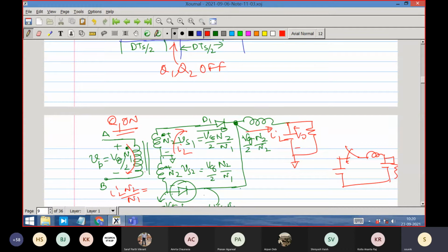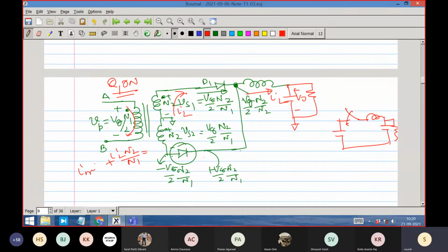That will be the first part, plus the magnetizing current, so that IMP plus the reflected load current will be equal to IP. How to determine IMP we have already learned, but qualitatively, think that there is a magnetizing current flowing through this coil, and this is the load current reflected into the primary side, that is the primary current. Clearly you understand what is happening here, right?